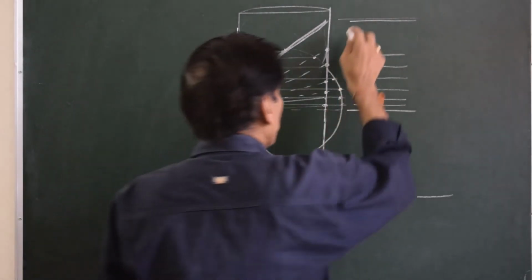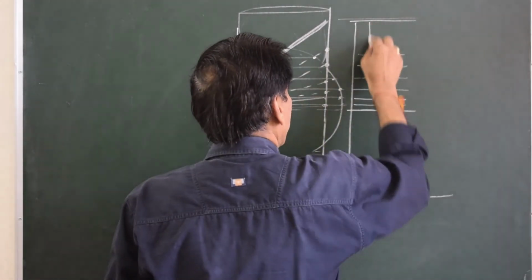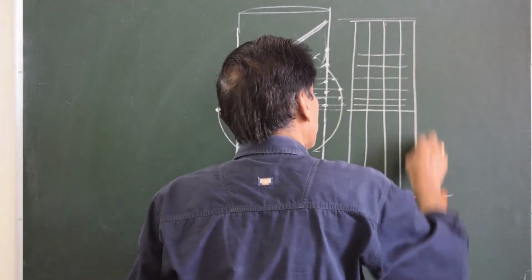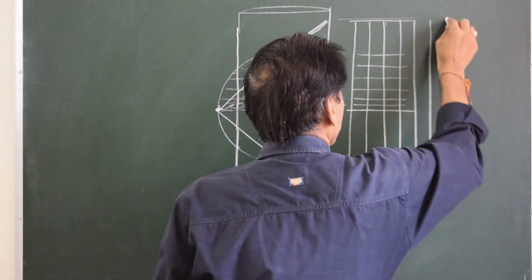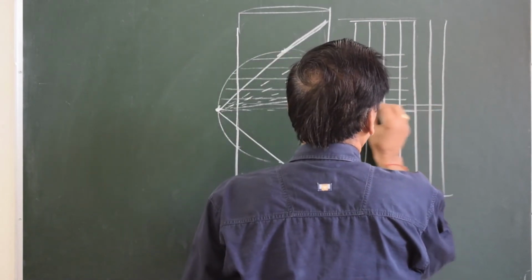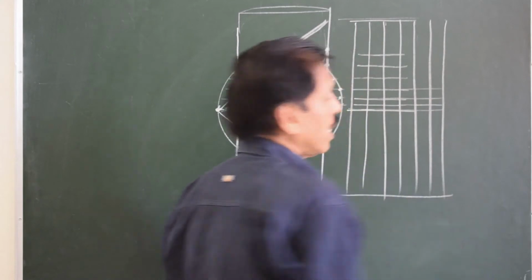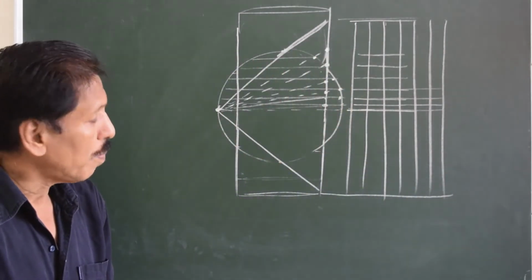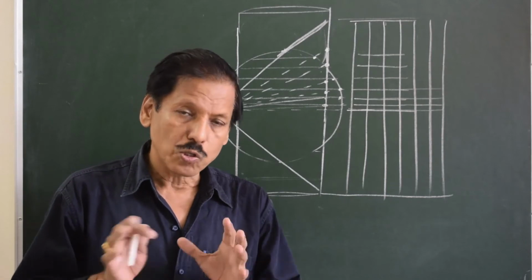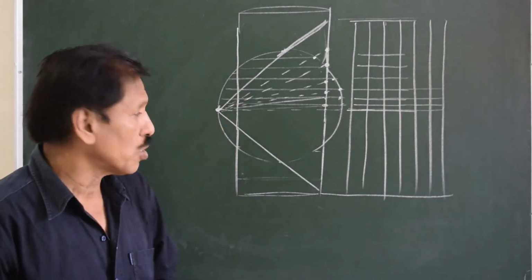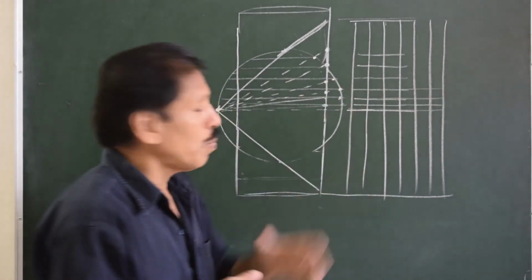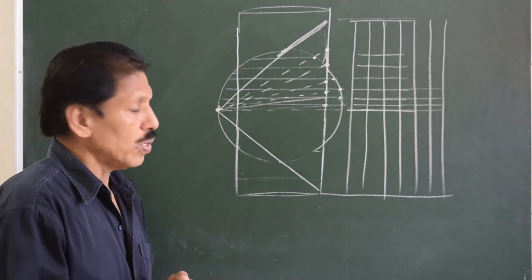Now in this projection, the meridians will be more or less equidistant parallel lines running north-south, whereas parallels of latitude are east-west running parallel lines with increasing distance. If you talk about distortion, shape, orthomorphic nature, etc., everything is compromised, but the advantage compared to the Mercator projection is that the polar regions are also represented.